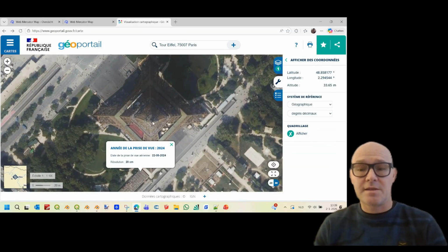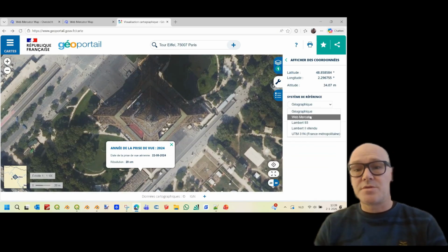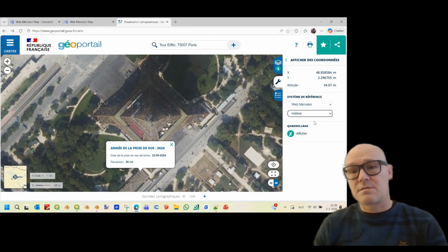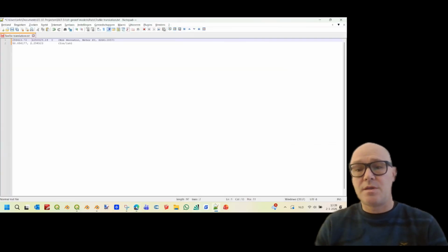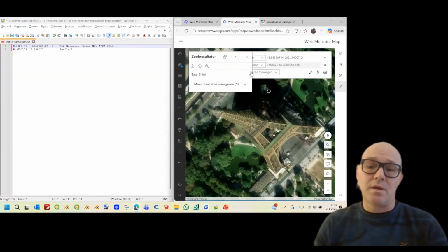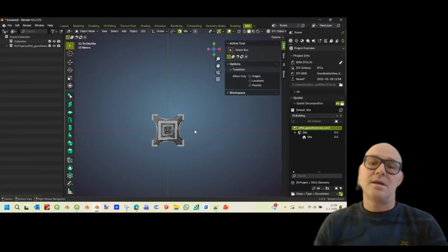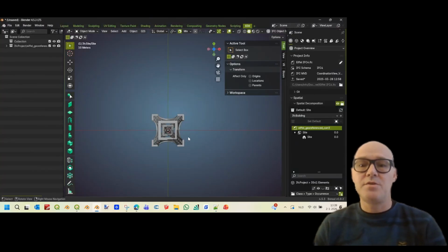As a matter of fact, every country has its own geoportal, which also shows these values. There isn't a spot on the earth that keeps any secrets about what the XY value or the lon lat value should be. As a first step, I need to write down these values: the first line for WGS 84 Pseudo Mercator, and the other one is the lon lat value.